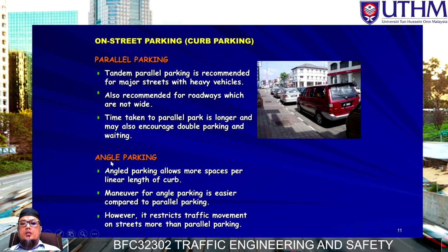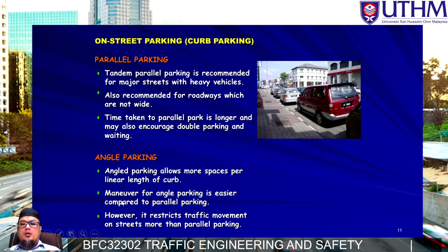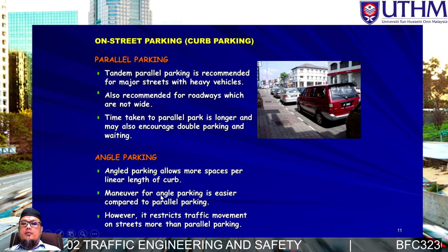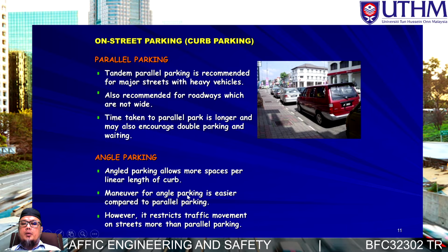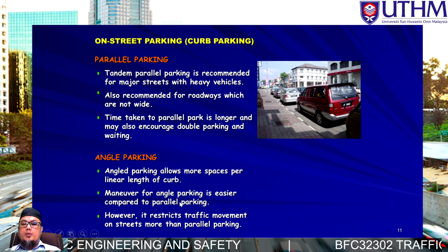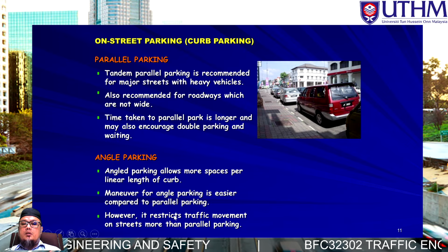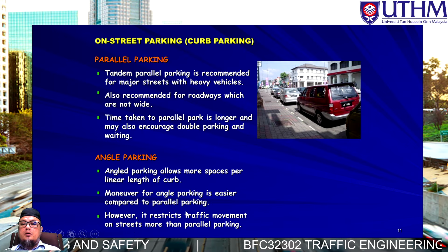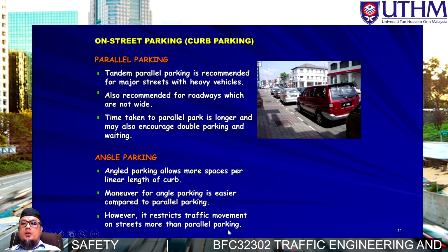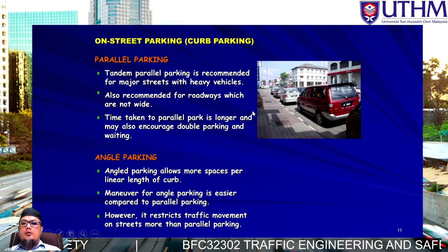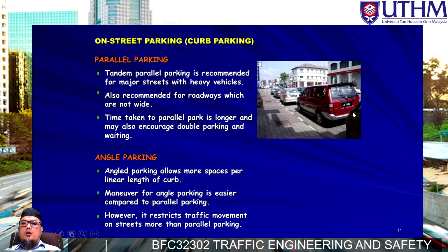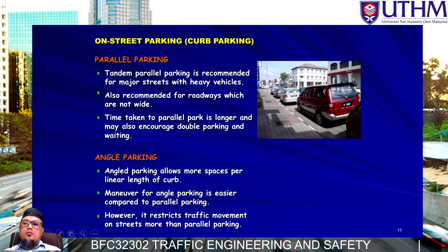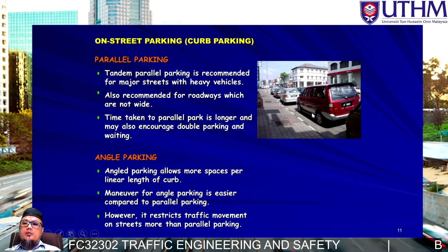Okay, there is also the type of angle parking. Angle parking allows more spaces per line of curb. Maneuvering for angle parking is easier compared to parallel parking. However, it restricts traffic movement on the street more than parallel parking. Parallel parking is not easy to go into. Parking is not quite easy. What more if you're going to reverse park?